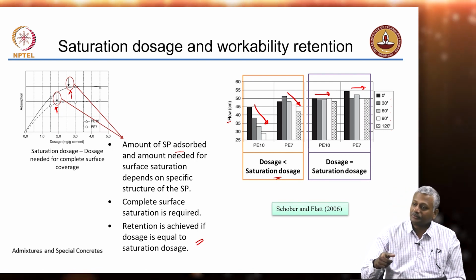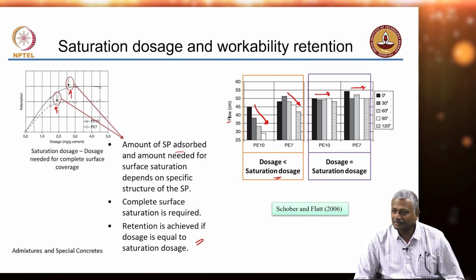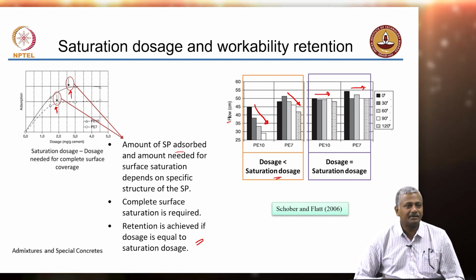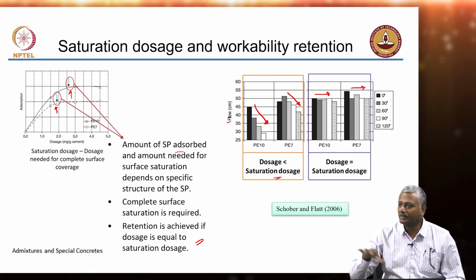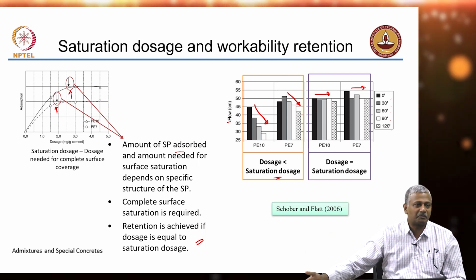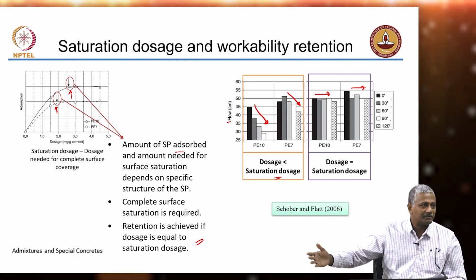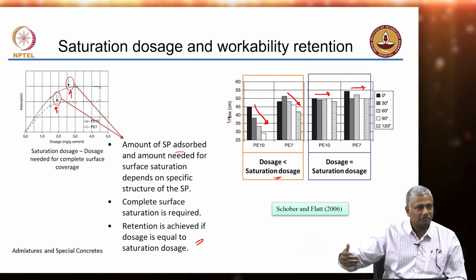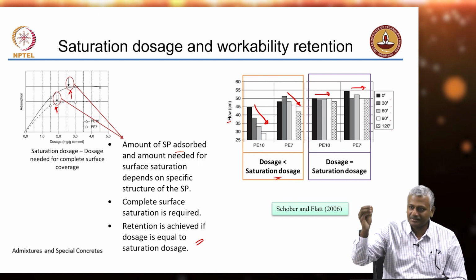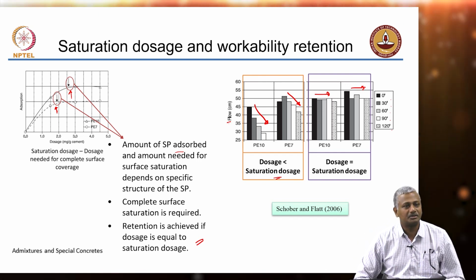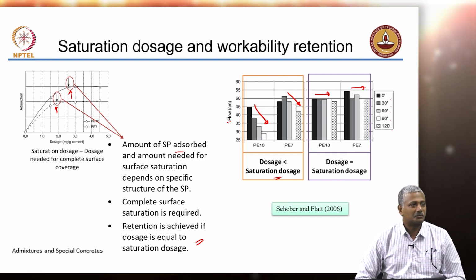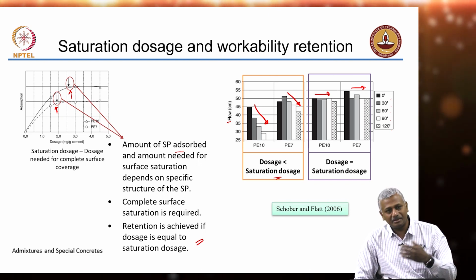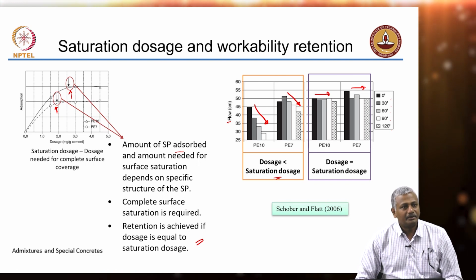So, when did they make the specimens? Before the concrete was delivered to the site, the truck stopped by the QC lab and discharged the concrete, and the specimens were prepared, nicely consolidated, stored in ideal curing conditions, perfect concrete. But at the site, extra admixtures were added, causing severe retardation, so it did not set. So, the problem is, even if you design concrete to meet a certain target requirement, the way you execute